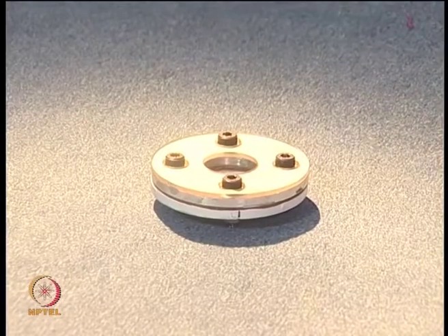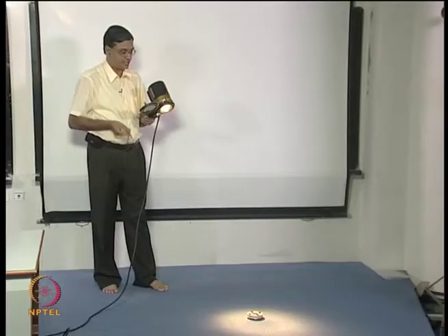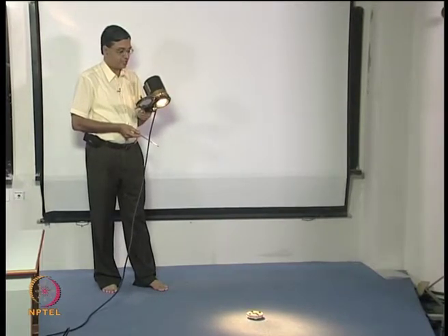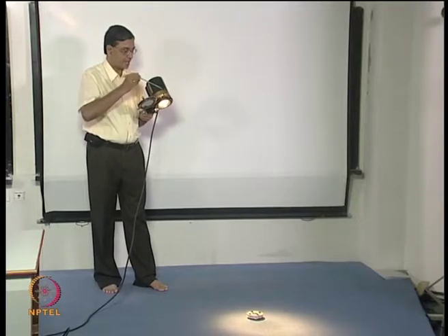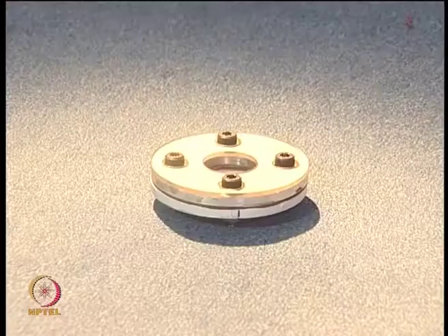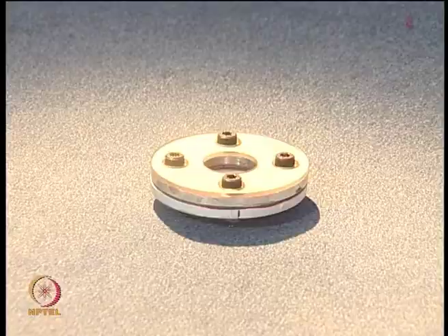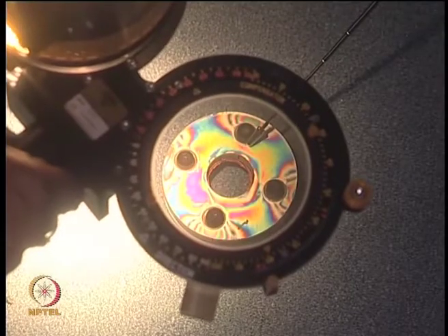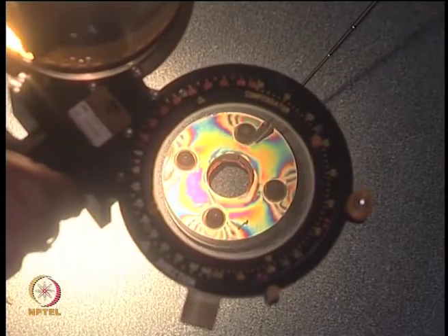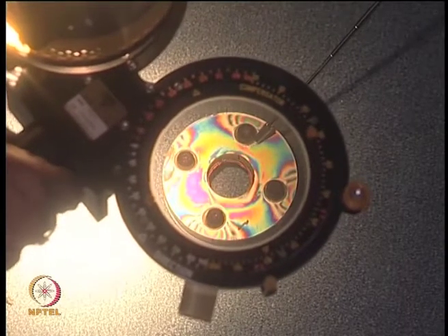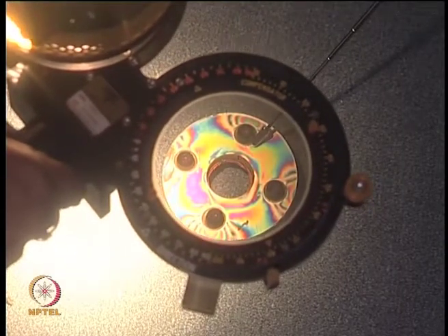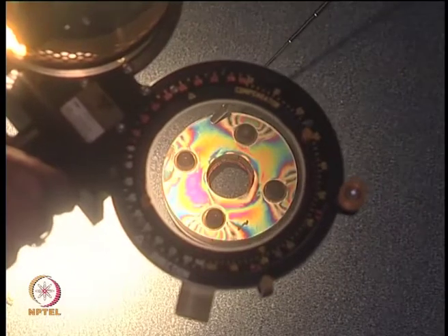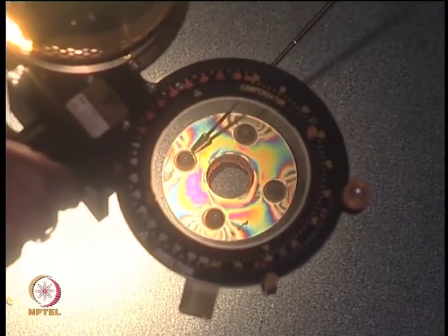I also keep the light source far away from the model, to reduce the angle of obliquity. So, the light impinges on the model, and the reflected light is viewed through the second quarter wave plate and analyzer combination, and I see rich fringe contours. For the benefit of the viewers, the human eye is replaced by an electronic camera for you to have a look at the fringe patterns.